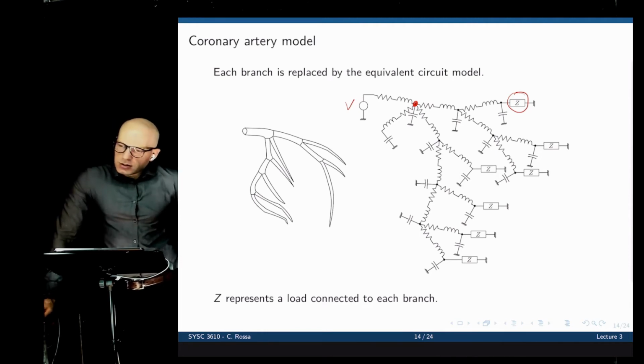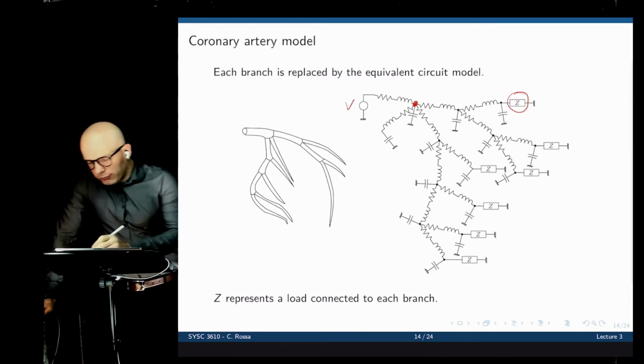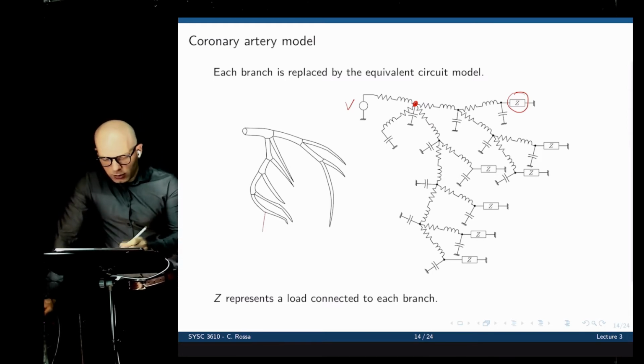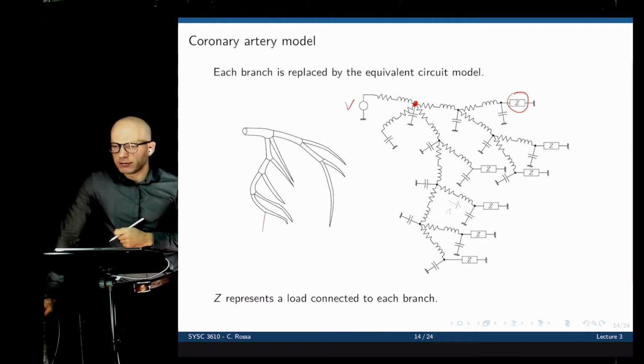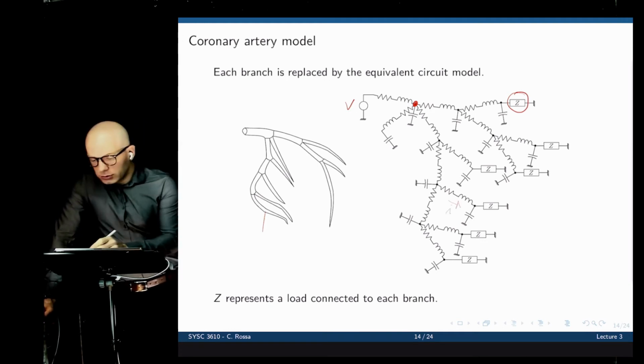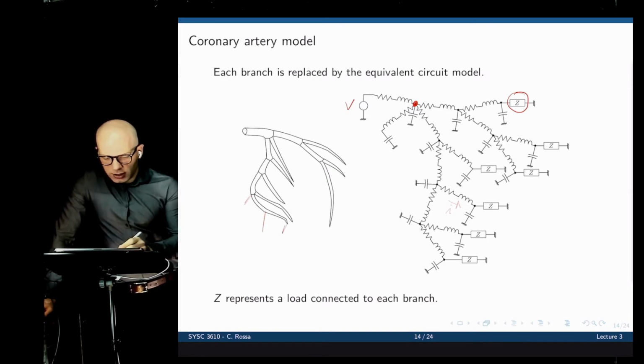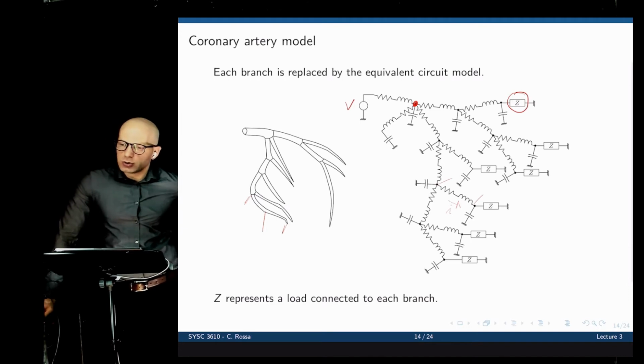So this becomes simply an electric circuit. And now we can solve for this. If you want to find the fluid flow here, we just look at the equivalent circuit and calculate the current out of that specific point there. If you want to know how much pressure is going through these points, just look at the voltage drop across those two points in the network, and so on.